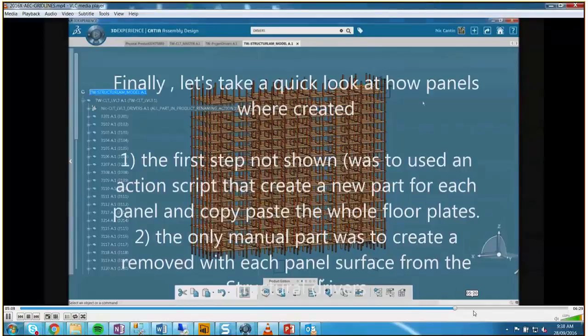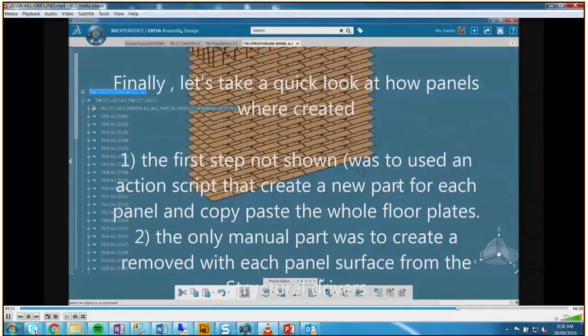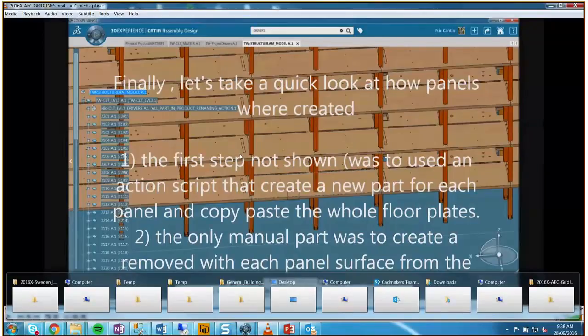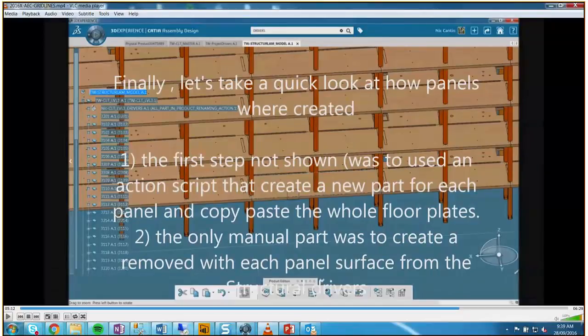And so you had multiple contexts where you were updating almost the first level of control geometry, and then the second level of dependent geometry, so that the model was partitioned in a way that you could update it quickly. Yeah, essentially we would update just the typical floors, and then it would propagate to the other contexts once we open those models, or we flip back to that next tab. So yeah, you're exactly right. We were in multiple contexts to quickly update.